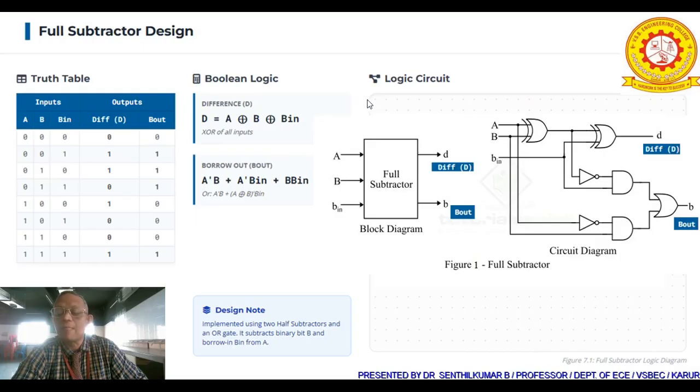Here we are choosing sum of product. So accordingly the derivation has been done for the function. If simplification is possible either by means of Boolean algebra or K-map, you try to do it and you put the final function. For the derived final function, then you go for the implementation. So this is the overall design procedure for any kind of combinational circuit. So I request the students to keep these things in your mind for the further complex combinational circuit design.